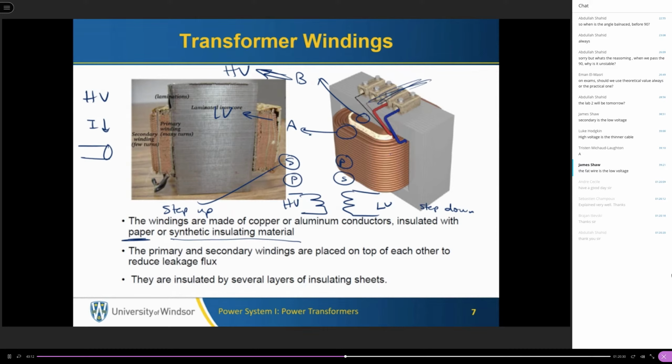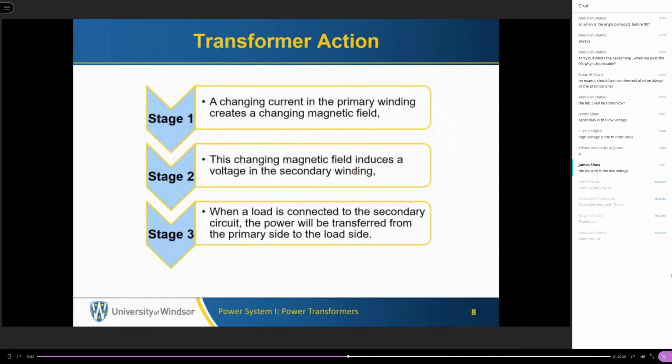here is broken down. So we may have a short circuit between 2 turns or 3 turns or 5 turns, or something like that. In this case, the transformer has to be disconnected. We may coil the winding again or replace it with a new transformer. Now let's review the transformer action.